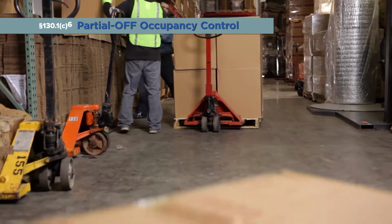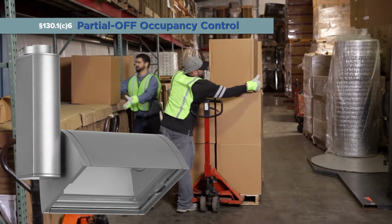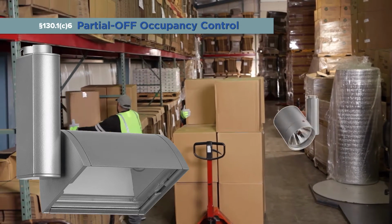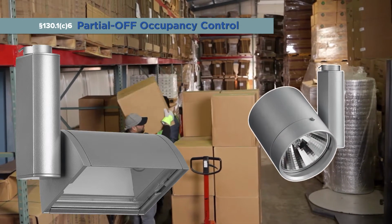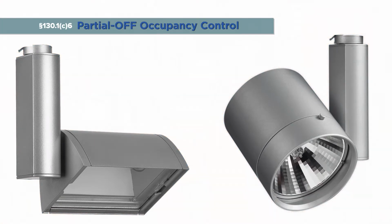Also, if metal halide lighting or high-pressure sodium lighting is installed in warehouses, occupant sensing controls can reduce lighting power by 40%. This exception is in place to account for the fact that metal halide lighting is difficult to dim past 50% of full output.